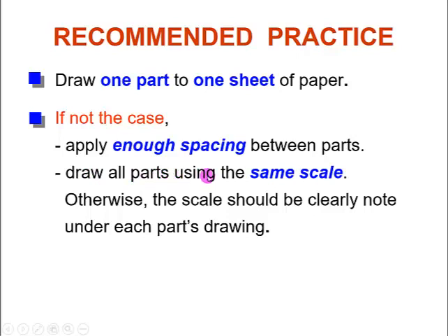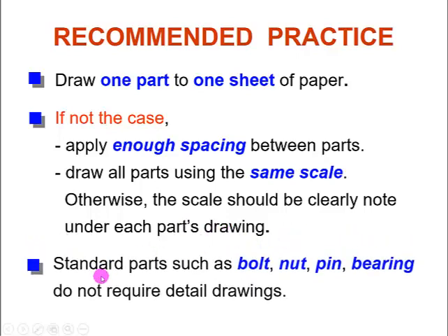Draw all parts using the same scale. Otherwise, the scale should be clearly noted under each part's drawing. You have to make sure that it's clear. Standard parts such as bolt, nut, pin, bearing do not require a detailed drawing. Just say your bolt, what the standard metric size is, just say it is a standard part.